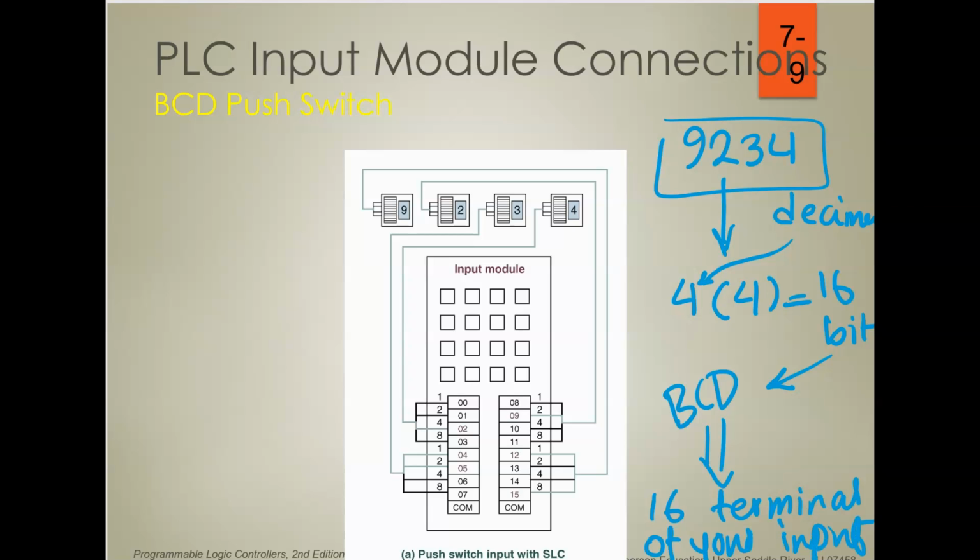So based on how many decimal digits you need to enter, you have to decide how many of your input terminals will be used by wiring to the push switches.